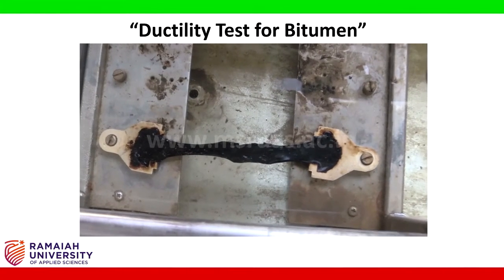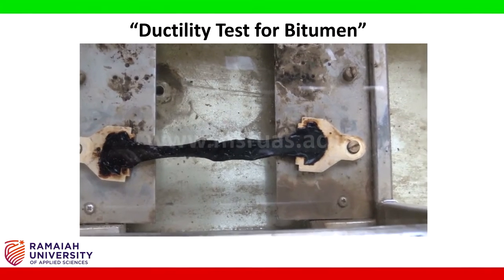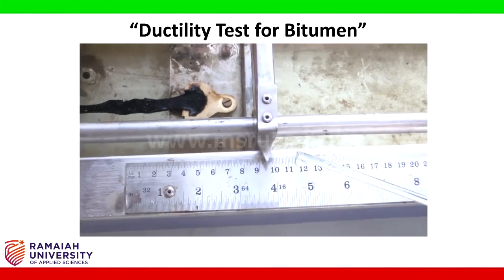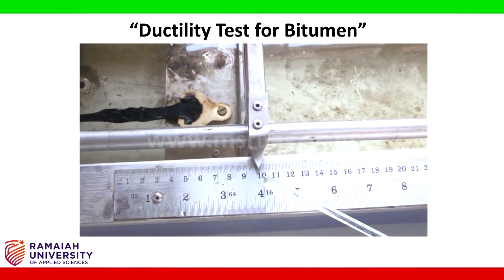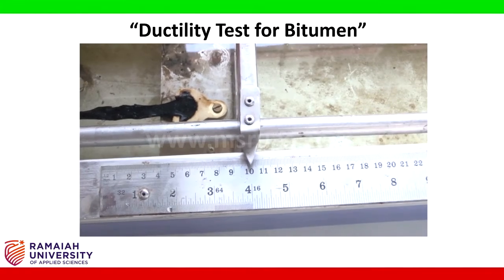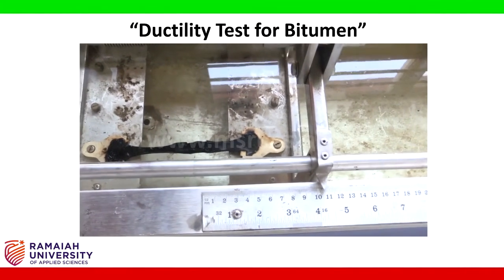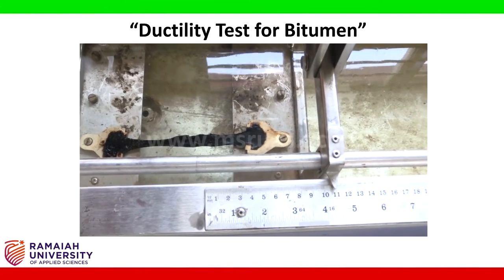What's happening here is this bitumen sample is elongating. If you keenly observe, there is a graduated scale attached to this moving system. Our failure will be considered under 3 conditions. One, you start elongating this sample, and at one particular reading your thread formation happens and the thread cuts.